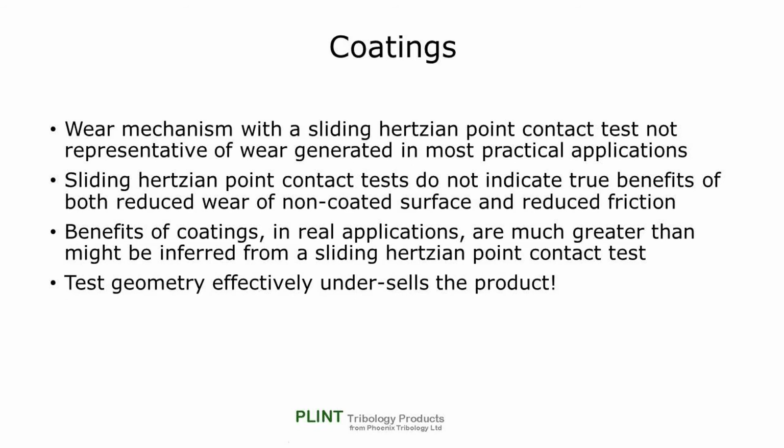The wear mechanism with a sliding Hertzian point contact test is not representative of the wear generated in most practical applications, and although the results of steel ball on coated flat tests may indicate some of the frictional benefits of coatings, they do not indicate the true benefits of both reduced wear of the non-coated surface and reduced friction.